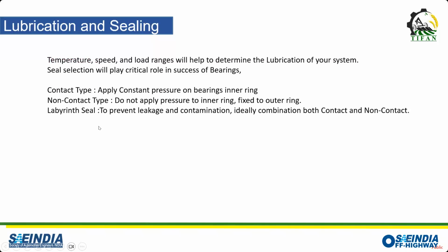Basically, like I said, you need to enter the inner diameter, outer diameter, width, and then the load ratings, both the load ratings. If you enter them, then some recommended bearings will appear automatically, and you can select one and then go into the market and purchase it easily.